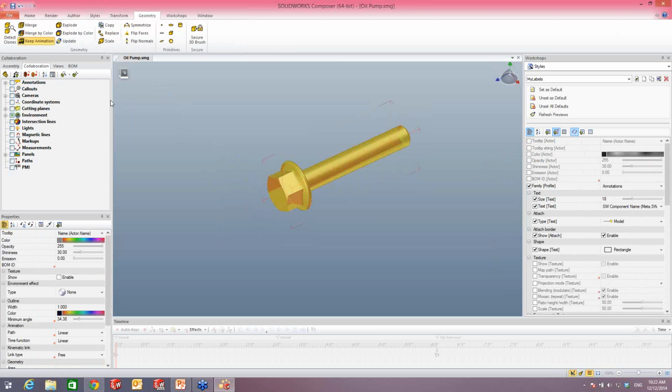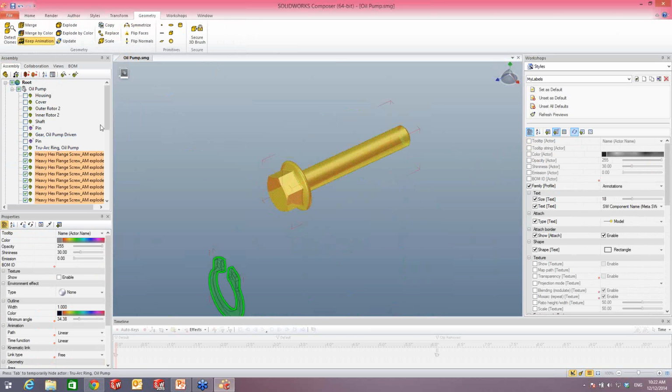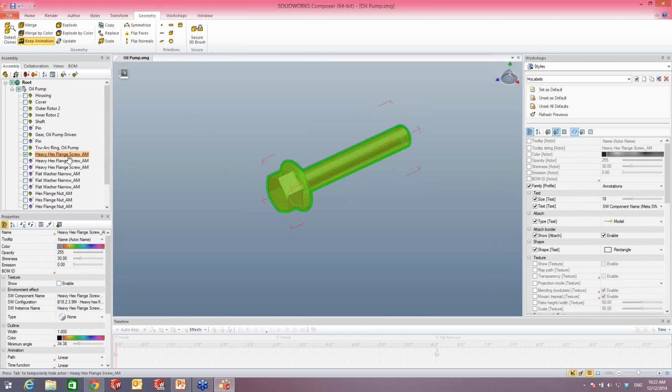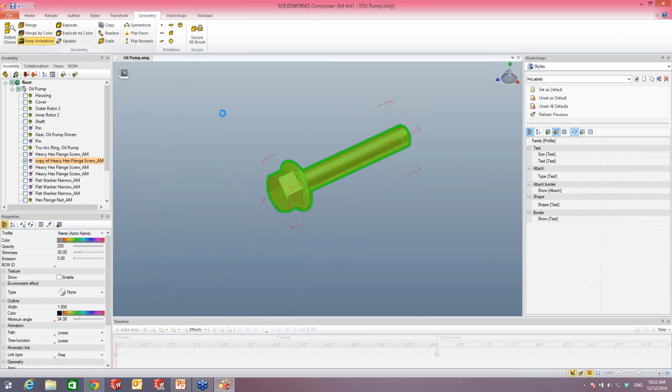Once you do that, be aware, it will, of course, show a whole bunch of new actors in that tree. My recommendation, undo that, is to select the actor. Make a copy of the actor. With that actor selected on the Geometry tab, you can copy it. Maybe then just turn off the original so you don't affect that. Okay? So with the copy, we'll explode.